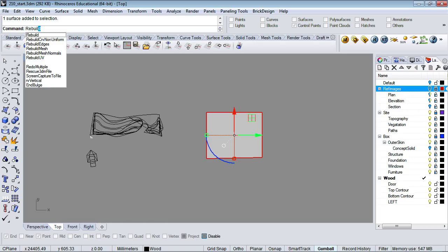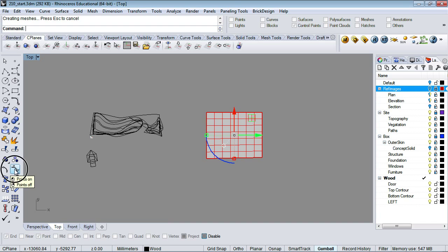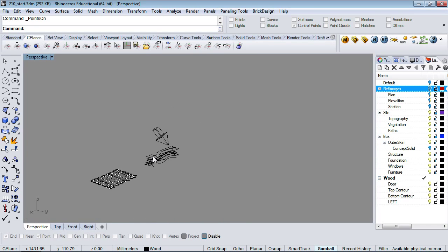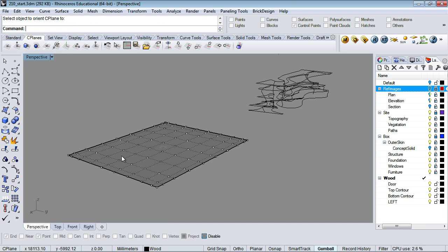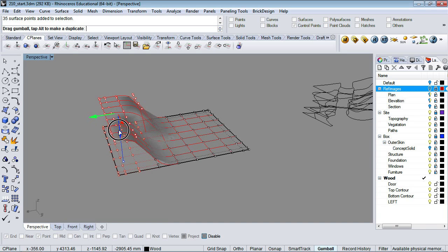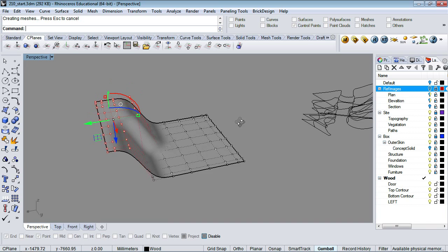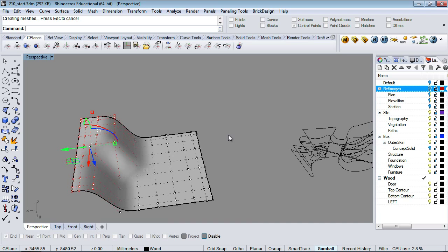You don't have to worry about this, but this is a flat plane, and sometimes you want to be able to modify this plane. So we can add control points to the plane, and then using our control point editor, we can go around and select these points, and I can just move them up. So that would be another way, if you wanted to be a sculptor, right? You could create a plane that has some holes, and then you can just sculpt it to fit that space. But I think that would be more tedious than making cross-sectional curves, actually.